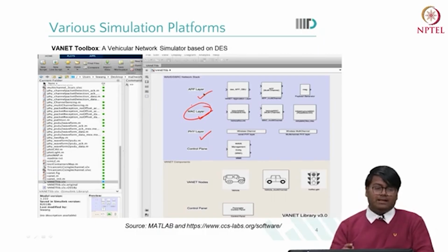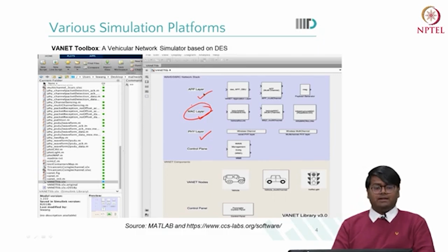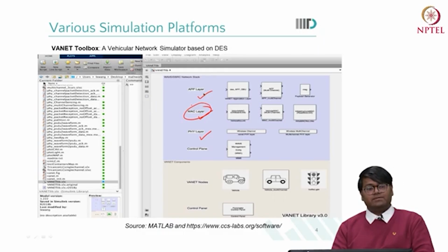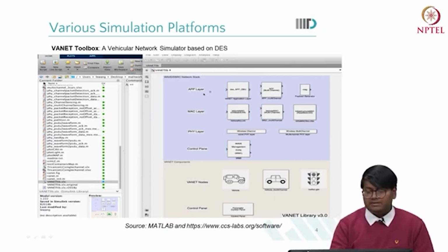Second, we have the MAC layer. According to IEEE 802.11p, this MAC layer uses EDCA, or enhanced distributed channel access. The application layer message intensity is transformed to a frame intensity which goes through a channel contention period before being transferred to the physical layer. Reliable data transmission, or RDT, also known as data acknowledgement, is supported by this MAC layer.